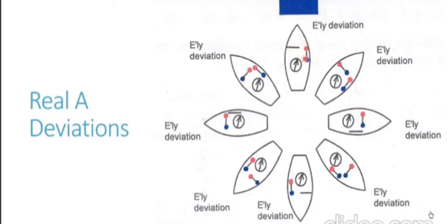Let's now concentrate our attention on the fore and aft longitudinal. The fore and aft longitudinal, if you look carefully, is aligned exactly in the same direction in which the Earth's magnetic field lies. The magnetic field lines are in the north-south orientation. The fore and aft longitudinal is also exactly in the north-south orientation. So it is perfectly aligned with the magnetic field, and this tells us that there will be maximum induction in the fore and aft longitudinal. Having maximum induction, it will become a strong magnet.